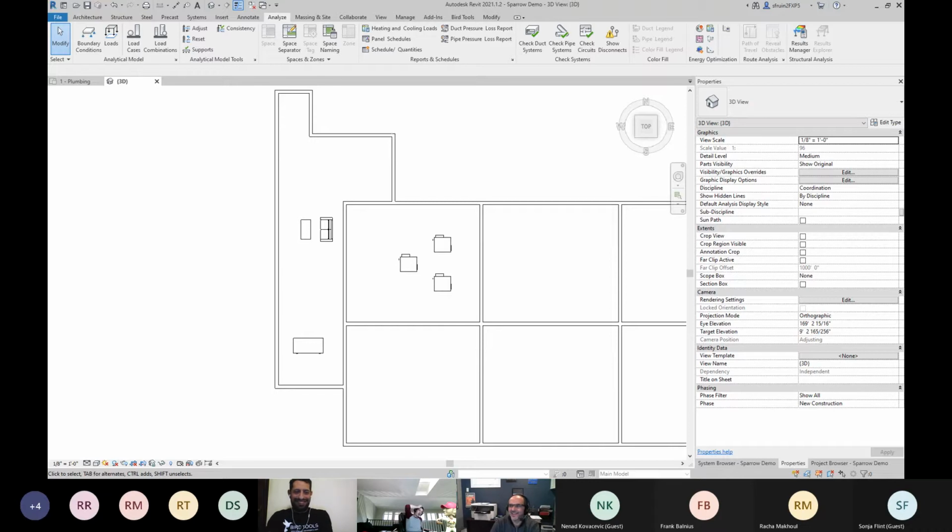Yeah, and I think that's part of all this automation, computational design, establishing this Revit family. And I would say more, if you're placing stuff with Dynamo, you really need to know where your insertion point is for that family. You know what I mean? So if something sits on the ceiling and it's not hosted, you need to know exactly.